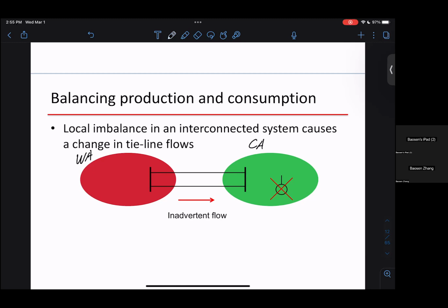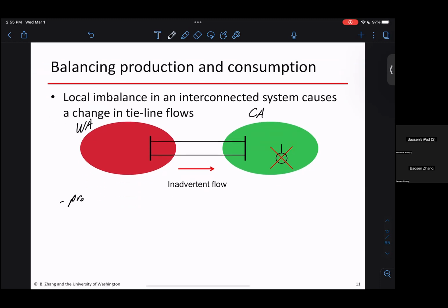If you have too much flow on this line, the protection would trip. You would almost never wait until something actually physically bad happens to the line. You have protection systems on the lines. The protection doesn't necessarily know what exactly is going on, but the way it's set is, it measures a large current flow, and it will trip, it will open this too. And then this can lead to further imbalance.